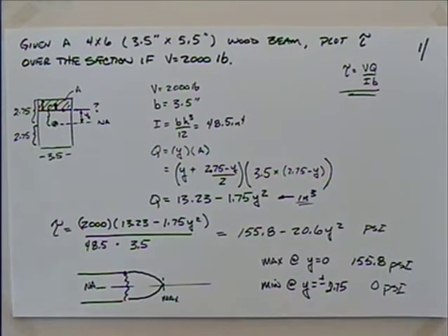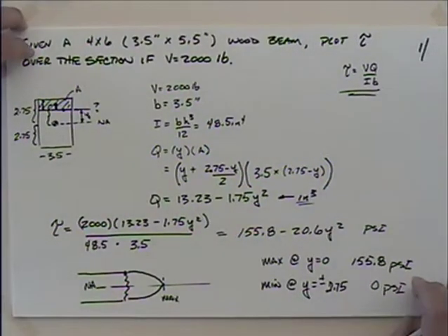So while we said that with our bending stresses we had 0 at the middle, we actually have maximum shear stresses at the middle. So before we start cutting the middle out of everything, because there's no bending stresses in there, we have to be careful, there are shear stresses. Although shear stresses are, in many cases, not as difficult to deal with as bending stresses. Questions with that then? That's just for a section of square.